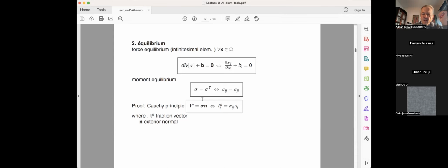Now, the stress tensor was really the contribution of Cauchy to the theory of continuum mechanics. This was the first notion of a tensor. You took a unit vector exterior normal. Typically, you can order your stresses into a table. Imagine these are the components sitting on the facets of an infinitesimal cube, which is aligned with the axes x1, x2, and x3. So you have these 3 by 3, these 9 components sitting around.